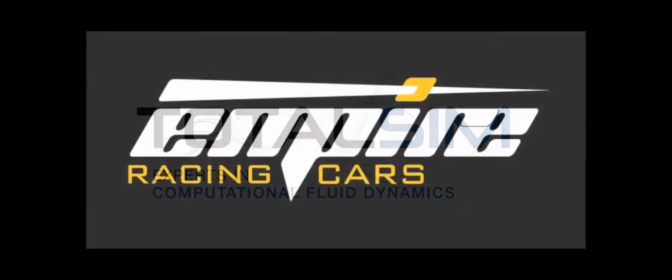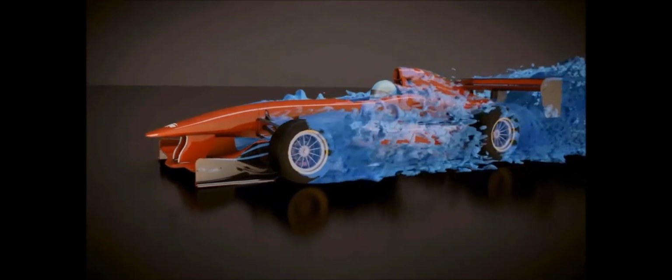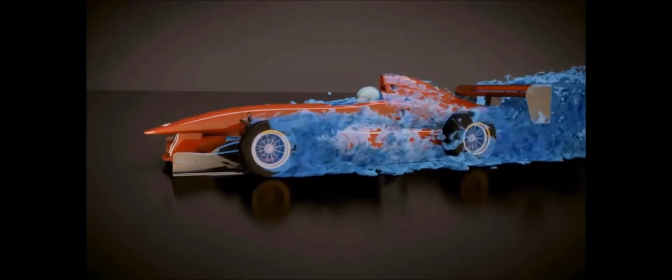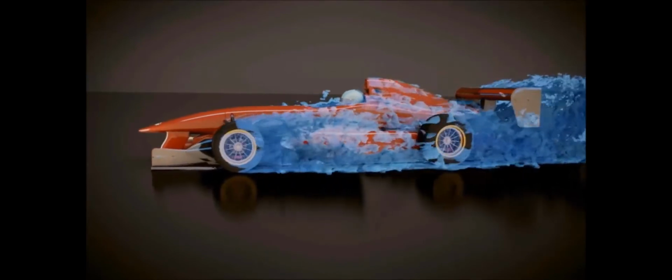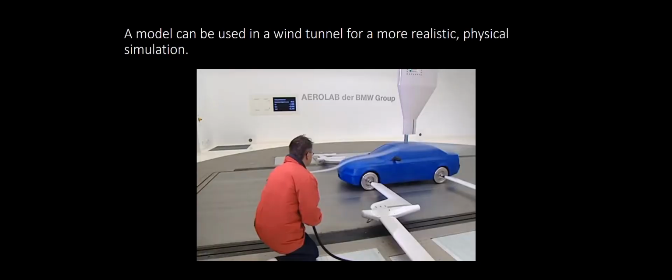After a CAD model is created, a first step in determining the drag on an object is to use a computational fluid dynamics, or CFD, simulation, which is what this video is going to show. This simulation will provide a number for the drag coefficient that engineers can use in their calculations. The next step could be to test a small-scale model of the object in a wind tunnel to calculate a real-world value for the drag coefficient.